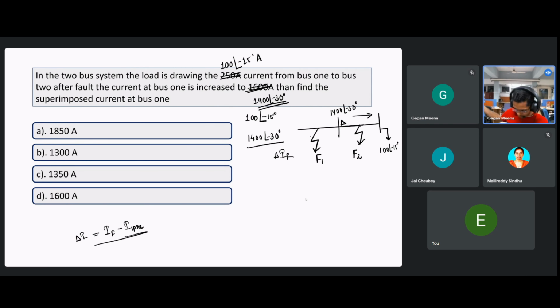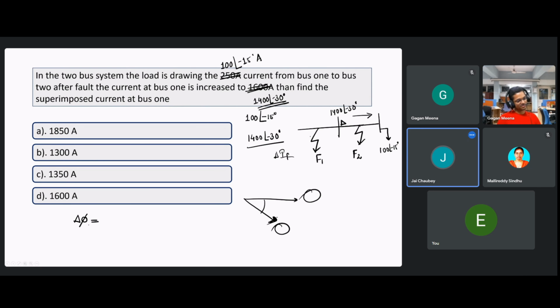So in a conventional relay, what are we doing? We take voltage as a reference and we measure the angle of current with respect to voltage. So what are these two quantities in the case of superimposed? Which one is the reference? If you recall the formula of the angle, from there you can tell what the formula for this is. How do we calculate this angle?